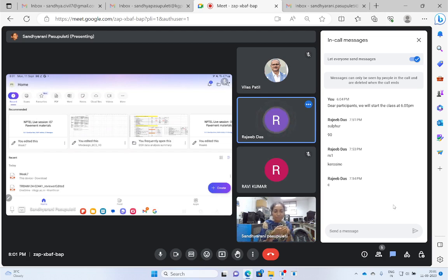At higher temperatures, even if there is permanent deformation, after the vehicle moves away, after a particular amount of time, it will come back to the original position. So it is beneficial for higher temperature resistance also. As far as fatigue is concerned, it may bend when the load is applied, but it will not develop any crack at the bottom because it is not brittle now. It is elastic in nature.